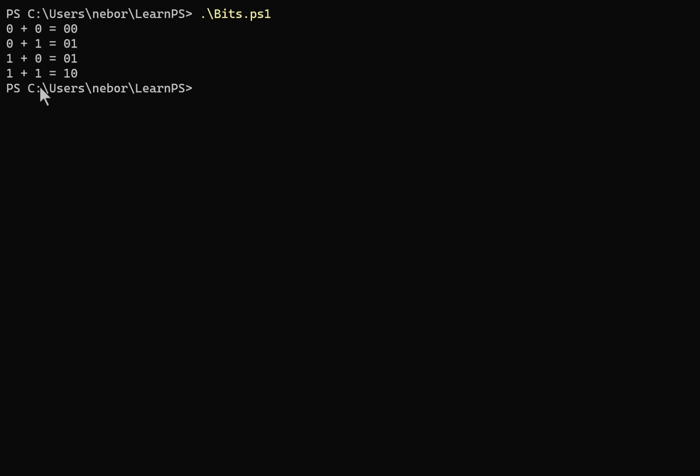And if we get 1 plus 1, that's 2. So that means that our high order bit, our bit 1 of the result, is 1. And the low order bit of the result is 0 because binary 1, 0 is 2. So the 0 is going to be in the output column of the addition, and the 1 has to be carried over to the next column. So that's our half adder.